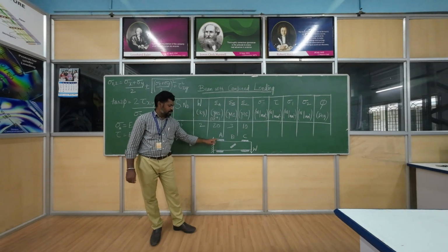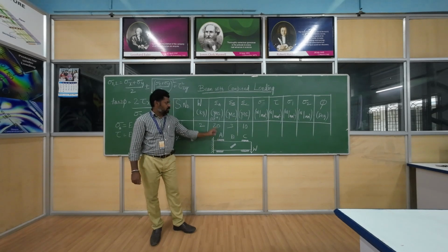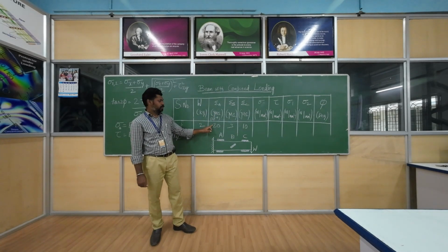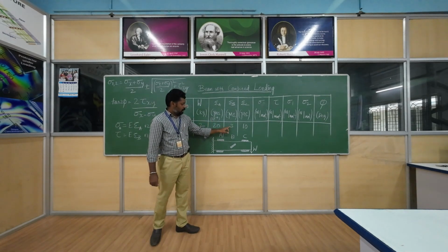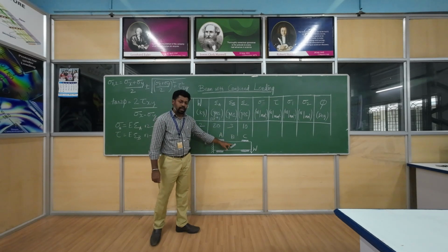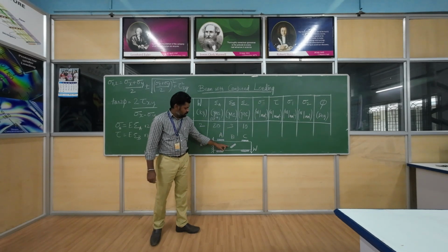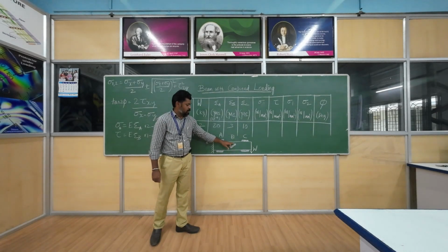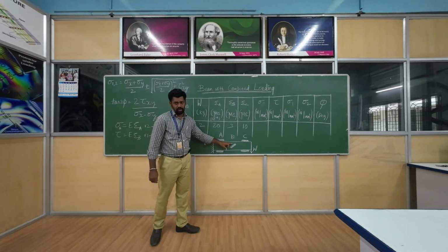So we have two strain gauges. From these strain gauges, I am getting a strain of 20 microstrain, that is 20 into 10 to the minus 6 strain. Now again, we also can get the strain at section B. As I mentioned earlier, this is the section where we are going to measure the shear strain. That is why this strain gauge is mounted at the angle of 45 degree.